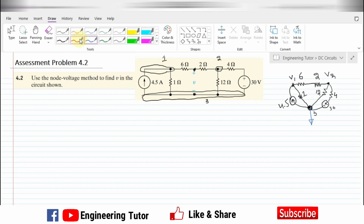Now applying KCL at each node of this circuit, let me call this one V1, and we can see that here we have some currents. The first one is I1, this current is I2, and this one is the third current, I3, which are flowing away from node 1. According to KCL, the sum of all the currents flowing away from a node is equal to 0.